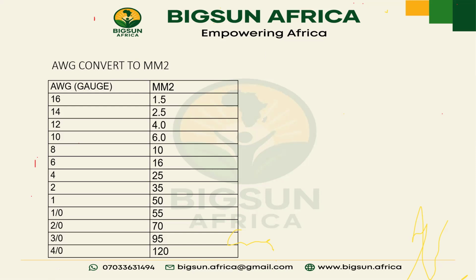Are you not forgetting something? When we are calculating our current, we will have what we call a safety factor. You think you are omitting it. So what should we use for that? The safety factor is 1.3. You are going to have your current multiplied by 1.3, then times the one-way distance. You have to have your total current first, before you multiply further.